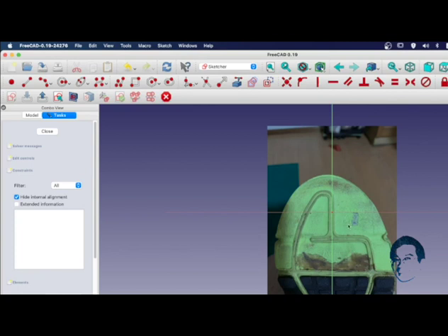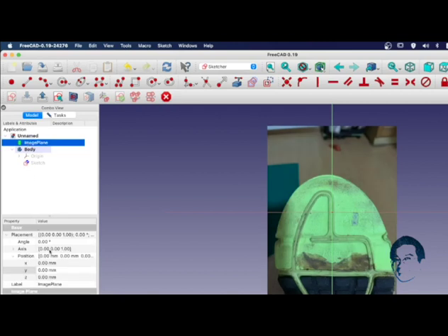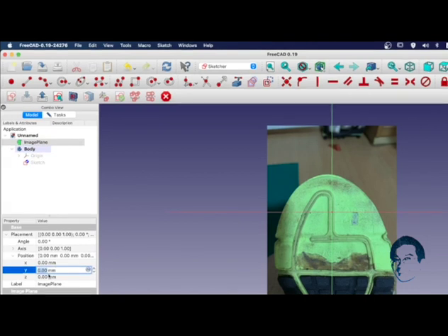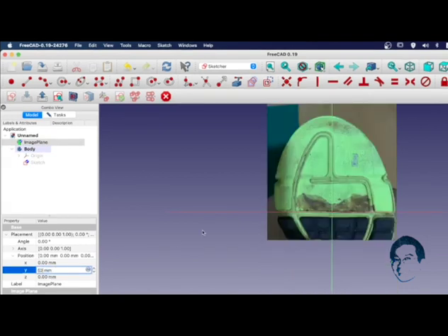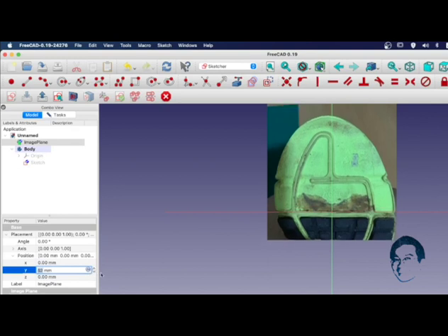To make it align to the axis, you can move this image up. To do that, go to the model here, select the plane, and in the position here, for the y-axis, I will move 52 mm up, or you can use the scrolling bar here to change the distance. As you can see, that is now near to the axis.